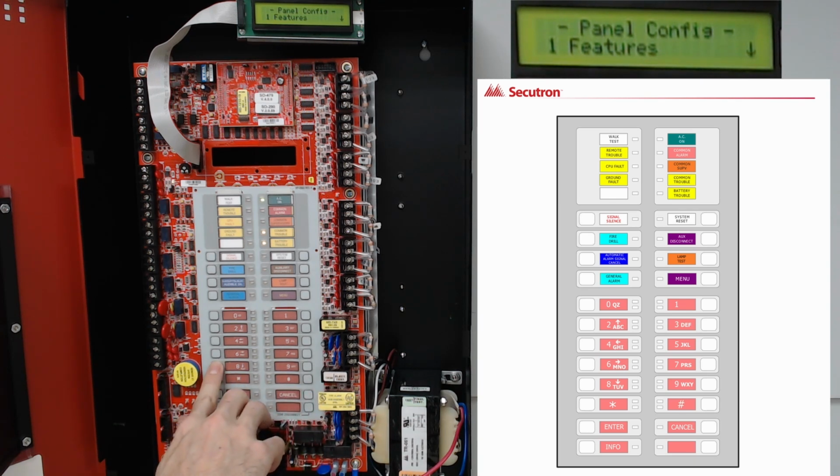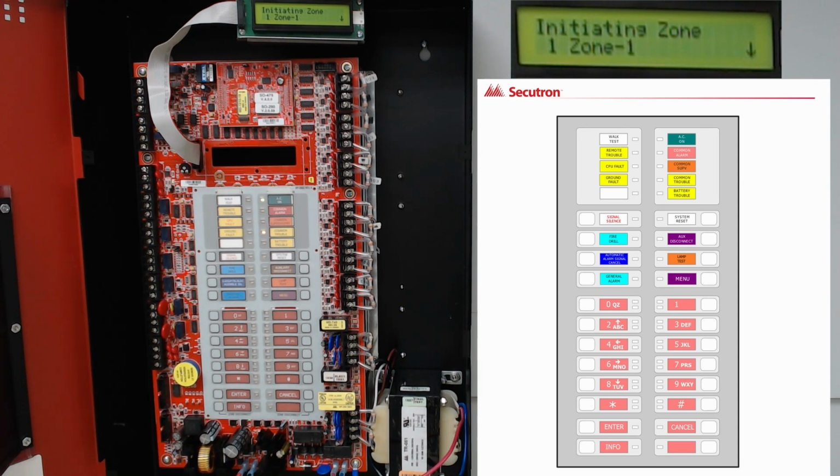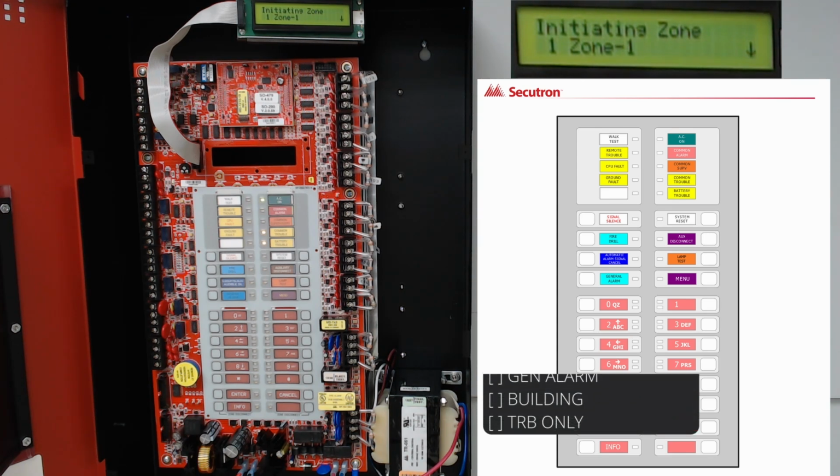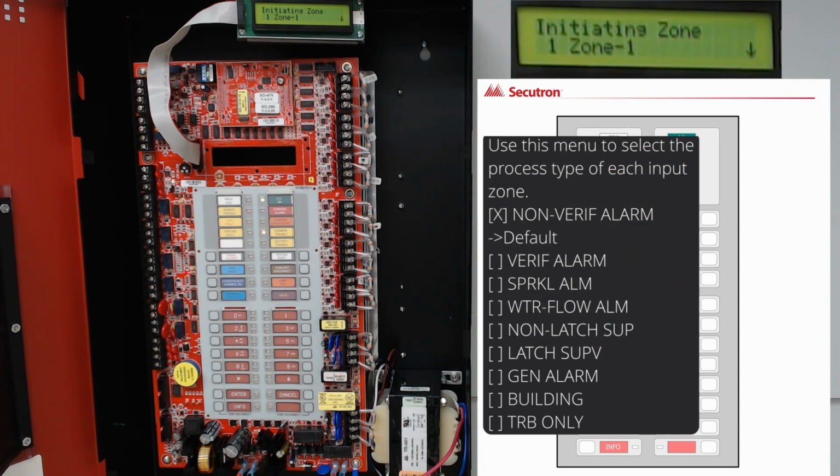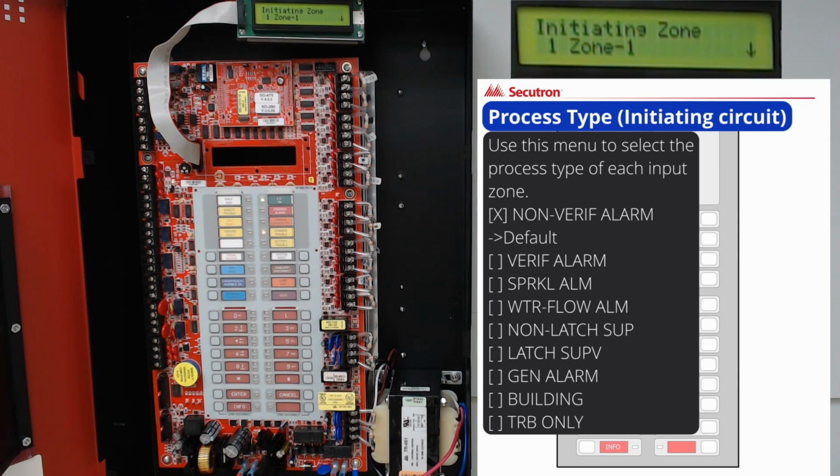By pressing the down cursor arrow, I can now enter into input zone by pressing enter. This input zone menu is used to program the process type for initiating circuits. The maximum number of initiating circuits is 12. Only those supported by the particular model are shown in the CFG300 configuration tool. The options we have, if we scroll through our initiating zones, will be the 12 zones we've spoken about.